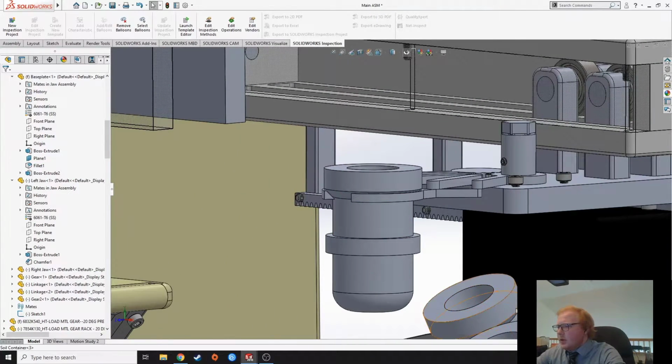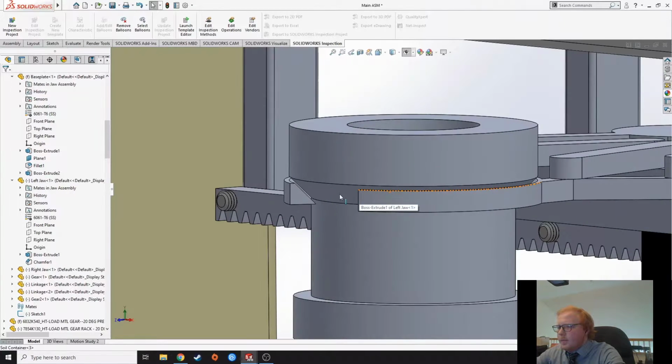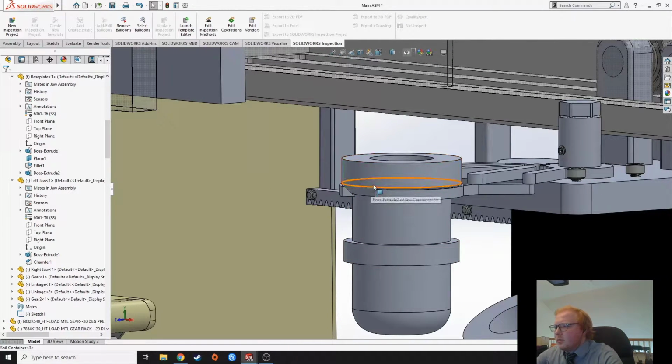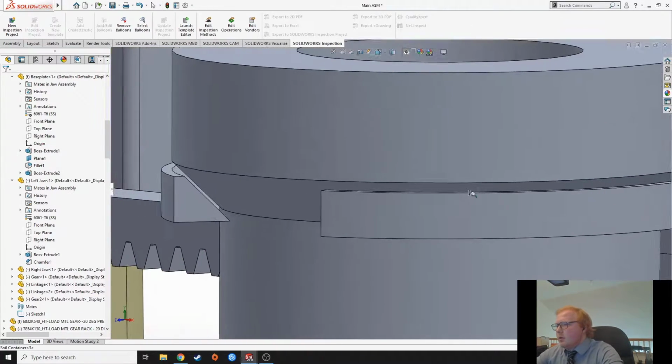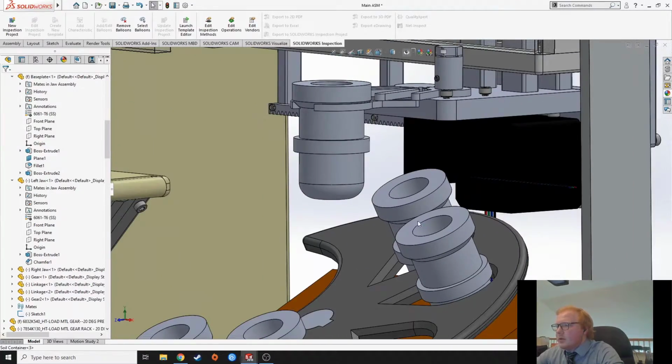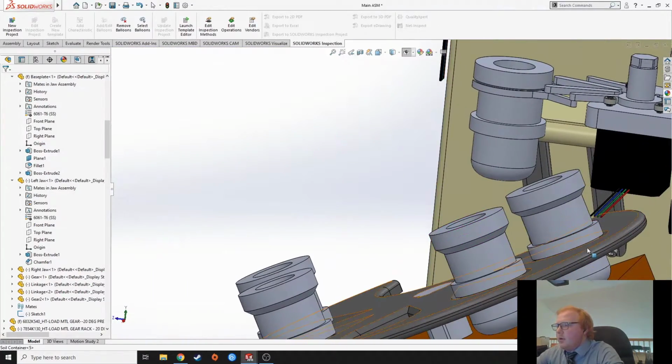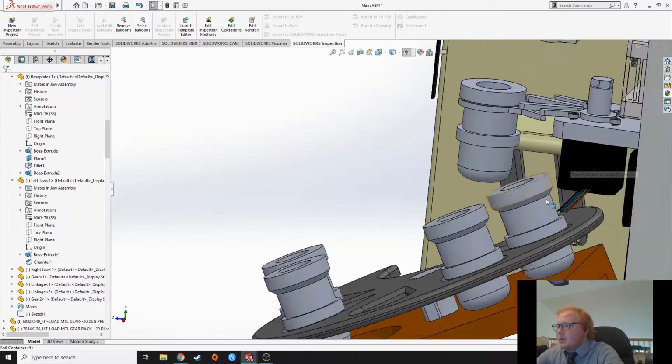And this mating surface here is so the sample container can be retained easier and allow for the clearance for the sample container to actually be retained by this chamfer here. And it will actually lift the sample container out as it grips the sample container.